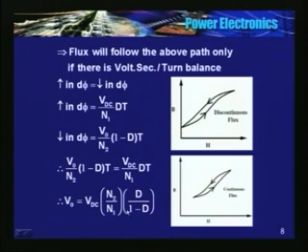So D divided by 1 minus D is nothing but a buck boost converter. The transfer function for buck boost is D divided by 1 minus D, but in addition to this term, there is N2 divided by N1, the turns ratio. Hence the name isolated buck boost.